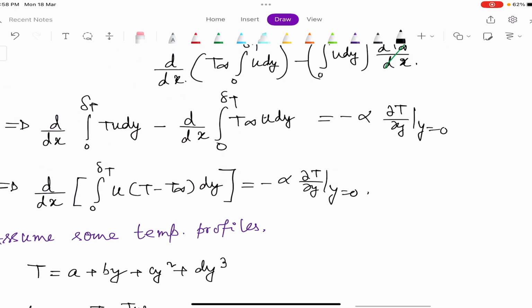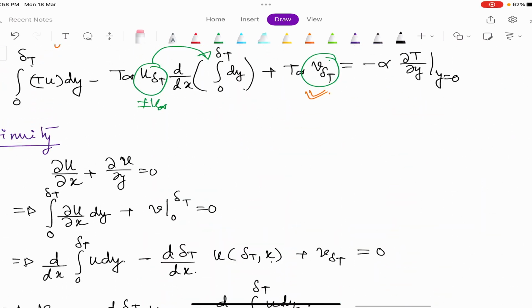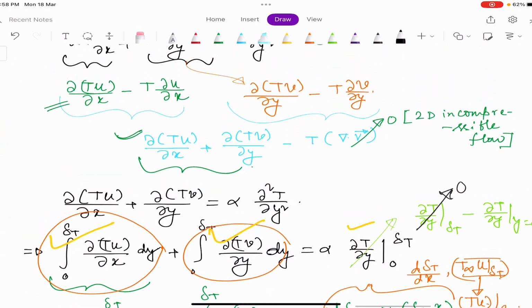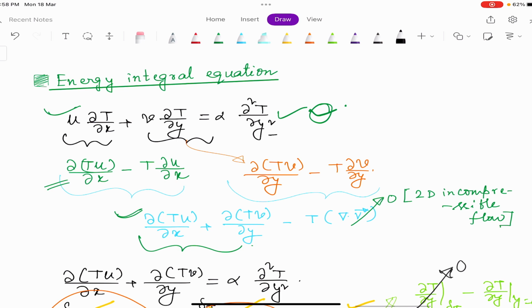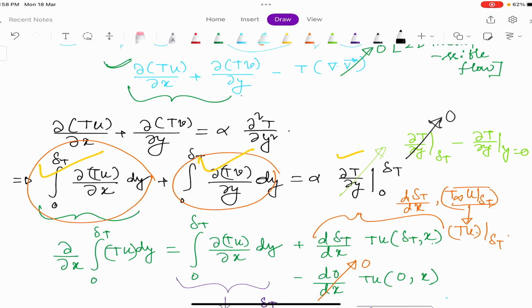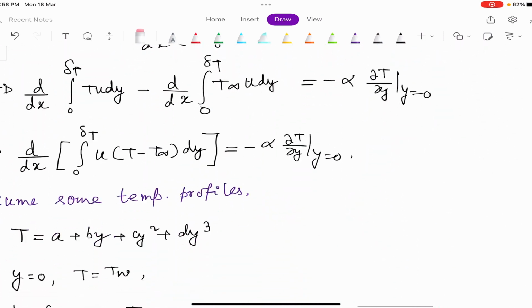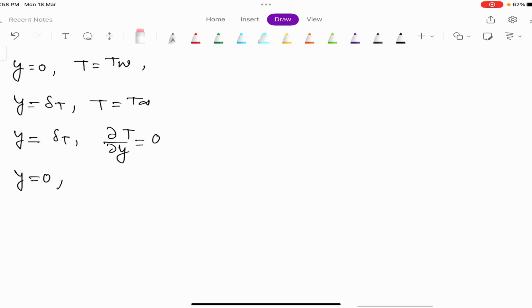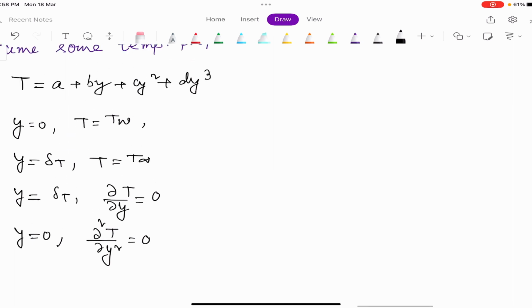what if you see the actual energy equation, this one. Okay, so at y equal to 0 you have u equal to 0 for no slip, v equal to 0 for no penetration, that means this is equal to 0. Okay, so I have seen that many students think that this is some boundary condition that we assume, but that is not the case. This has to come from the problem. Otherwise you cannot take this.